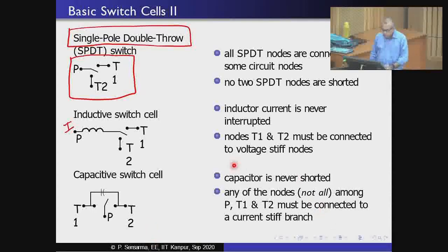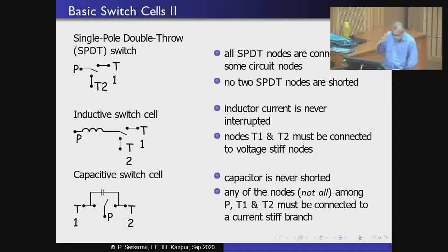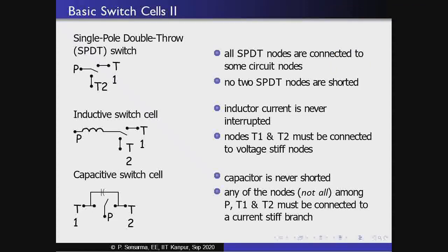In order to look at that, circuits. Now before, again we need to do one more little exercise. As you can fairly well appreciate, if you put a simple switch in series with an inductor, the moment the switch turns off, you go into a discontinuity. Now that, as we have so often previously emphasized, is not something that we are going to allow in the circuit. So we create a construct where we allow a possibility for the inductor current to flow irrespective of what the switch position is.